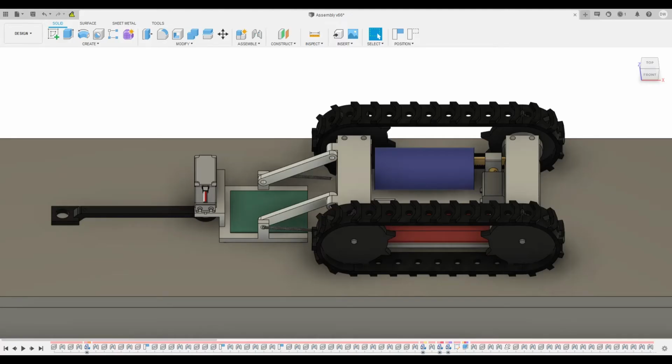The overall mechanical design for the robot utilizes a tracked vehicle with a large permanent magnet that will allow it to drive on beams in any orientation. The two tracks are individually controlled by two motors that will allow them to be used for both steering and driving the robot as it moves along the beam.